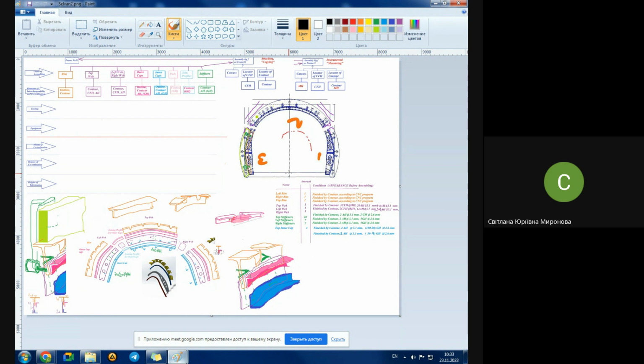Next, the workshop technologist, the workshop engineer, writes the technological process, and together with the technological process, creates the so-called scheme of jig, something that you do in your bachelor work. Next, on the base of this scheme of jig and all the previous materials plus technical requirements, such an engineer creates the assembly drawing, may create the model, of course a detailed 3D model of jig, and creates a drawing of the assembly jig.